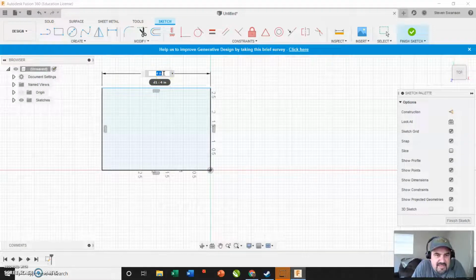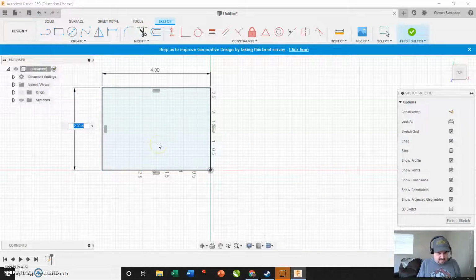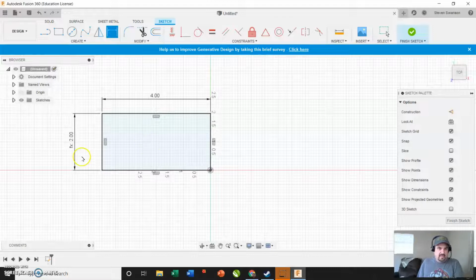Look at that. It says D1, and it says it's 4 inches. D1, that's dimension 1, okay? We're going to need to know that. So that's one constraint. Now watch this. I'm going to say from here to here has to be D1. And I'm going to say divided by 2. So this right here is now a parametric constraint.